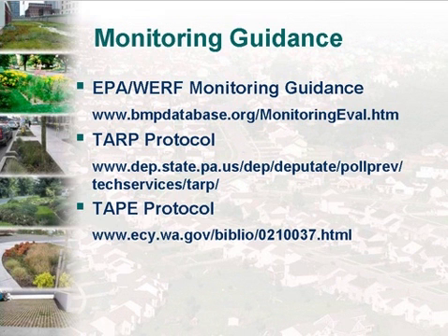The next slide shows some of the protocols that are out there, resources for you if you want to put together a monitoring program for a particular BMP. John, yours is the first one there. Yes. For those who are interested, if you go to the International BMP database website, you can download a pretty comprehensive document on monitoring guidance that our team has prepared. And then there are many other excellent protocols around the country. We've listed only two here. There's the TARP protocol, Technology Acceptance and Reciprocity Partnership Protocol, the coalition of 6 states. Then the TAPE protocol, developed by the Washington State Department of Ecology. And there are other good guidance documents on monitoring that you can find quite easily.